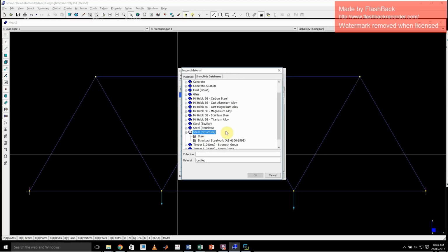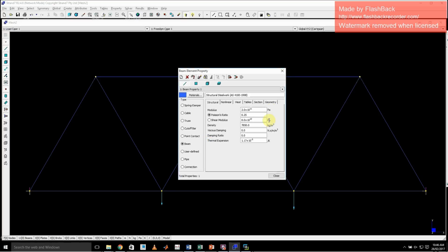So we can come into steel, pick structural steel here, it's a common one, that's great, and it will auto-fill this type of stuff in for us. Modulus is 200 gigapascals. That's a lot of zeros, that's pretty annoying to work in, and that's why we use this scientific notation. But it's also why, when I said pascals aren't always the best unit to work in, that's why. We also need to give our structure some geometry.